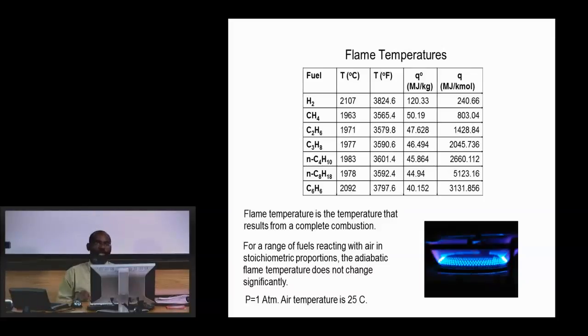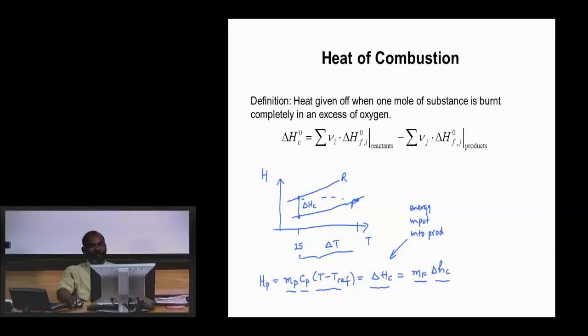So in a well-controlled laboratory experiment where you might, for example, have a laminar flame where the flame is just sitting there as an interface, and you can put a thermocouple or some other device very close to it or probe it, then you can really identify the flame temperature. Otherwise, you're measuring some average temperature. You've got soot, radiation. You've got all sorts of other losses.